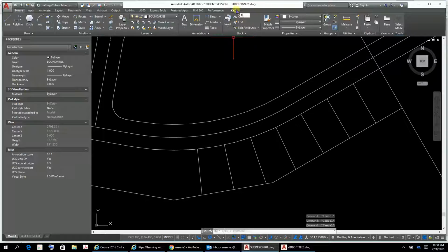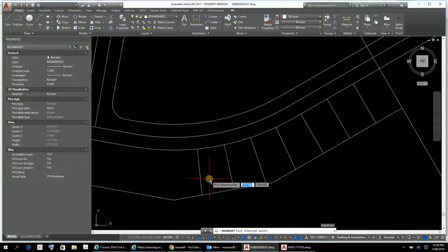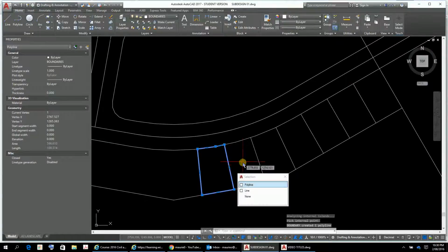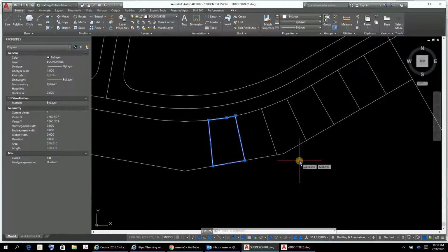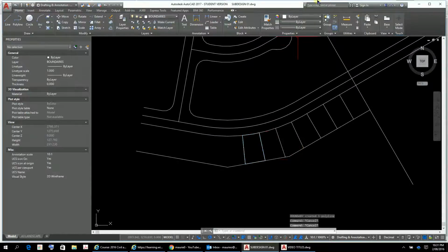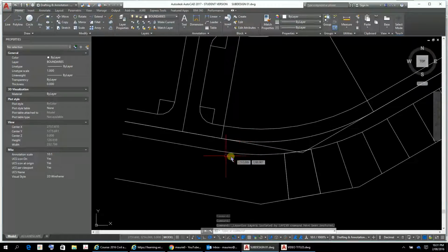So now I'll just do a BO to check. So the isolate has just selected the one layer, enter, and there's my boundary line. What's that area there? What have we got there? 596. Yep, I'm quite happy with that. That's round about 600. So I'm trying to keep these lots all on the thing. So now we just use the unisolate there. 596 is very close to 600. And we're coming round. We're still on the curves here till we get to here, and then it'll straighten up.